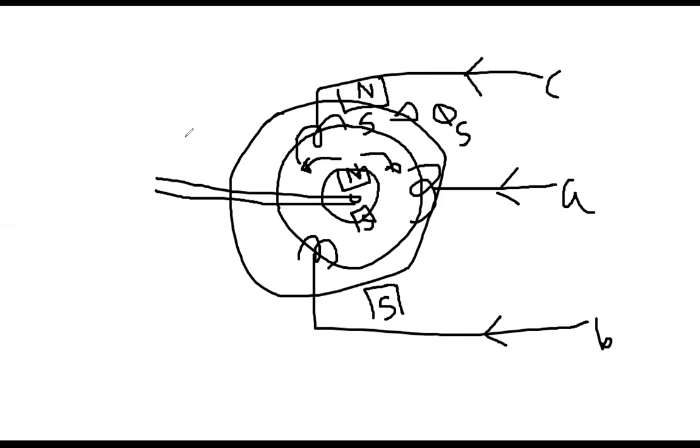That's why it is called that the synchronous motor is not self-starting. It cannot start by itself. So what is the goal here? If the motor does not start and I am discussing the synchronous motor, then what does that mean? We have to make it rotate. So what is done? Let's put an extra coil, which is called the damper coil, on this body. Why do I put that one? Because already, because of the application of three-phase voltage, that phi s is developed in the stator, and that is moving. Now there is a set of coil on this body. What will happen? This magnetic field will induce voltage in this coil. Before, there was no coil, but now I put a coil, there will be voltage, and consequently there will be current flow. There will be another flux, and let's designate this as phi d because this is the damper winding.